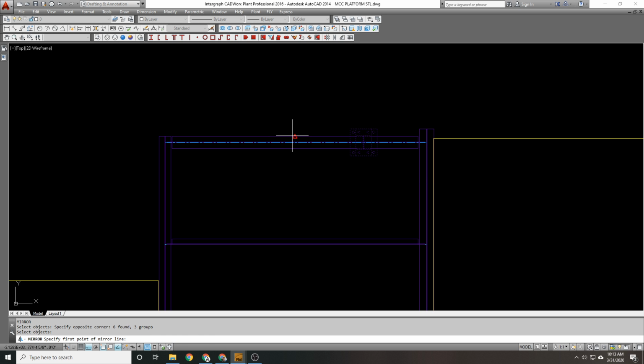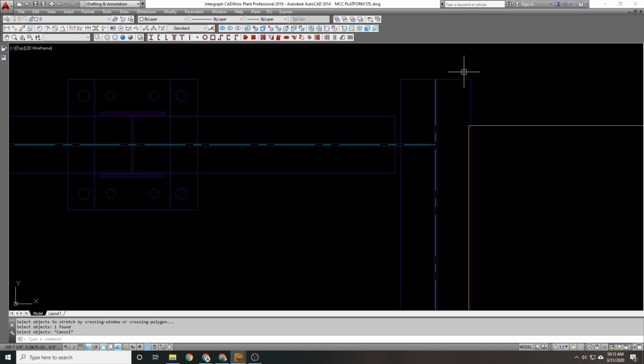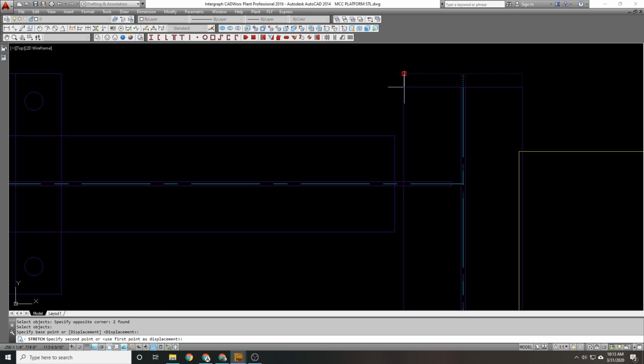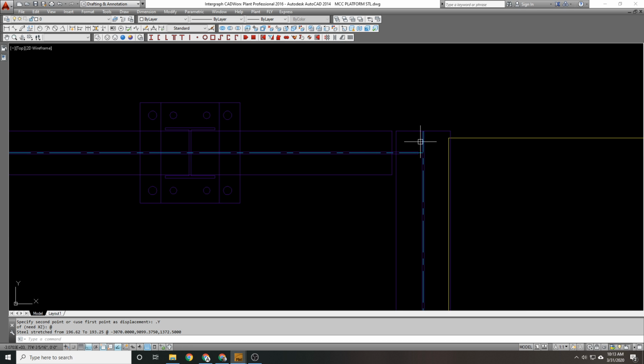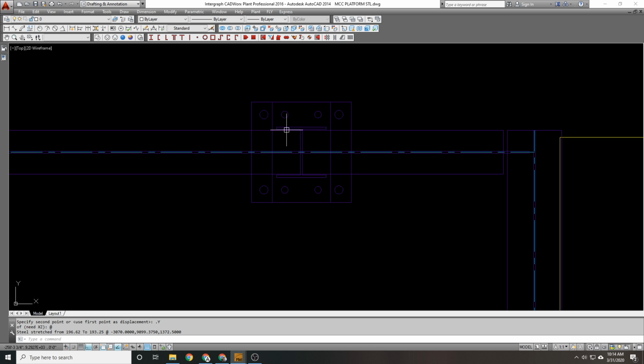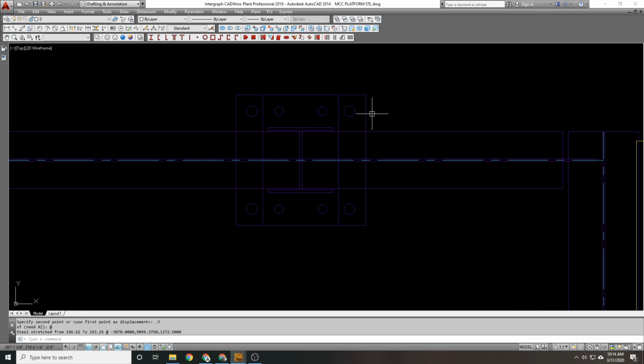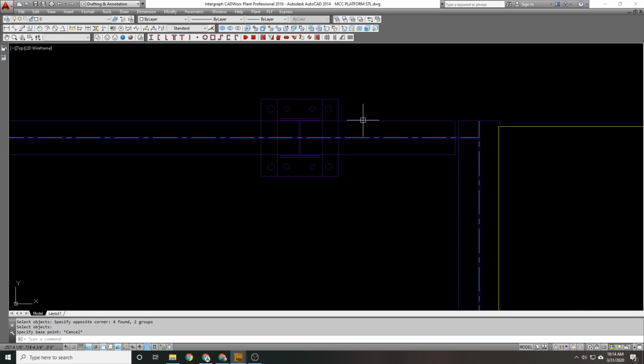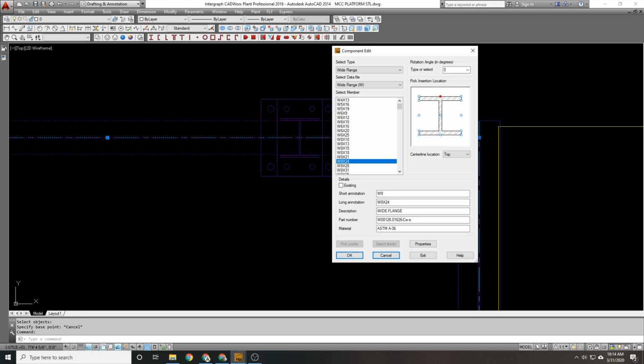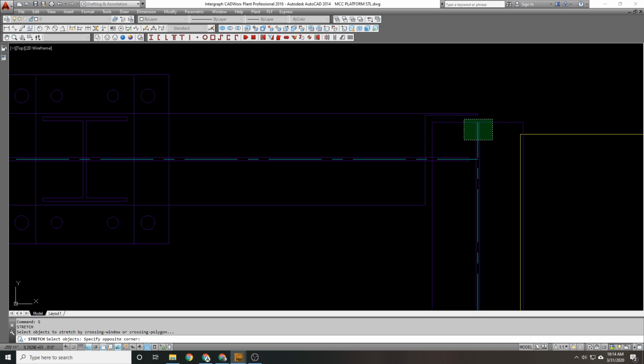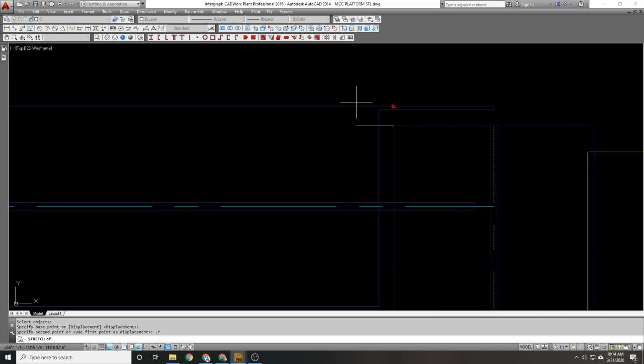I'm going to do a mirror. I think that should give me enough room for the foundations to clear each other when they do that. So I'm going to bring this back to where it was. I'm going to do dot Y so I match up to this beam here. Now here, what I can do is actually kind of easy. So it's not that bad that I did all this. I can just rotate this. And where this was 824, I might as well make all my perimeter beams 824 now that I'm thinking about it. So again, bring this dot Y up to here.